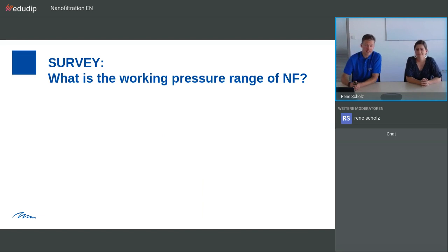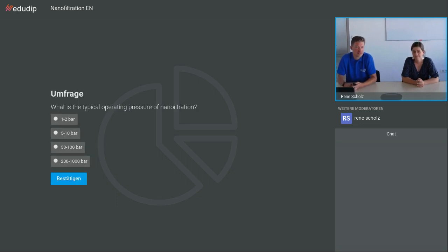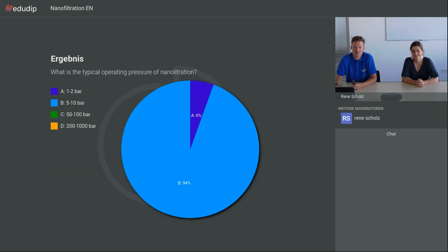All right, before we do another survey, just to check if you listened. So what is the actual working pressure of nanofiltration membranes? We have 1 to 2 bar, 5 to 10 bar, 50 to 100, or 200 to 1000 bar. Yeah, we have a really nice trend, so it looks really good. All right, so 5 to 10 bar is the typical range. It goes from, let's say, 3 to 20 bar, I think, is the complete range, but the usual operating range is between 5 and 10 bar. All right, thank you.